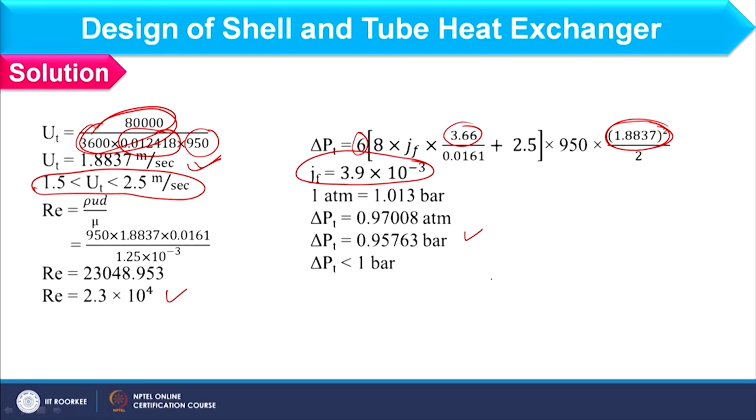Okay. So, what you have to do next, because you have changed the velocity, right. In that case, you also have to check the changes obtained in heat transfer coefficient calculation, because you have already changed the DI. Okay. So, it will not affect the shell dia, because shell dia will depend on OD of the tube, and OD of the tube is same, that is 3 by 4 inches. Okay. So, bundle dia, shell dia, L by D, all these values are not changing. Only change we can obtain in heat transfer coefficient in tube side, because here we have change in velocity.